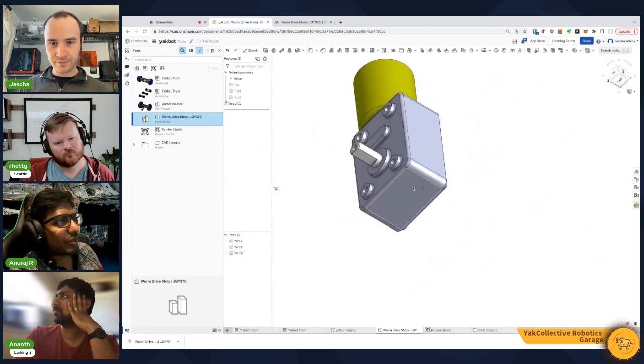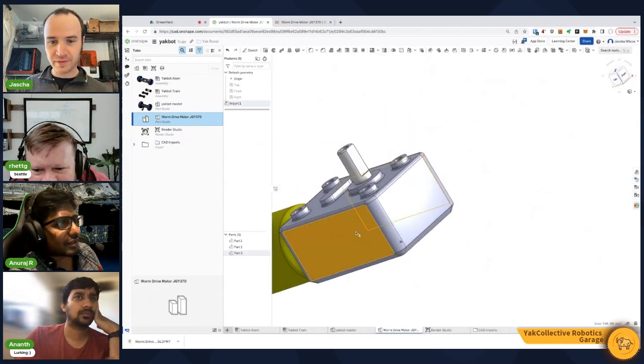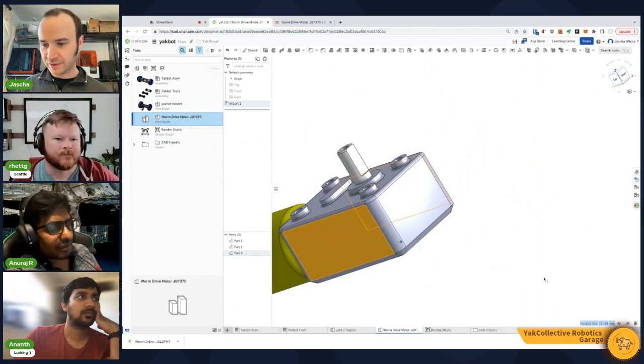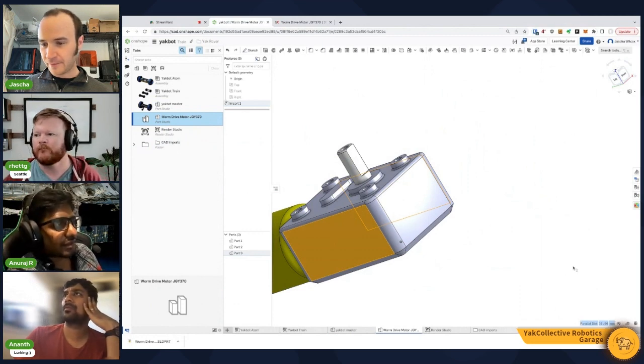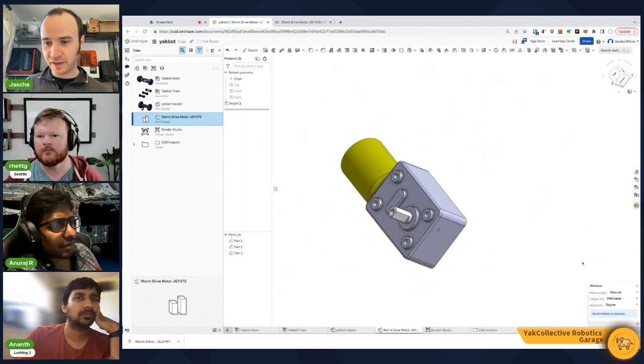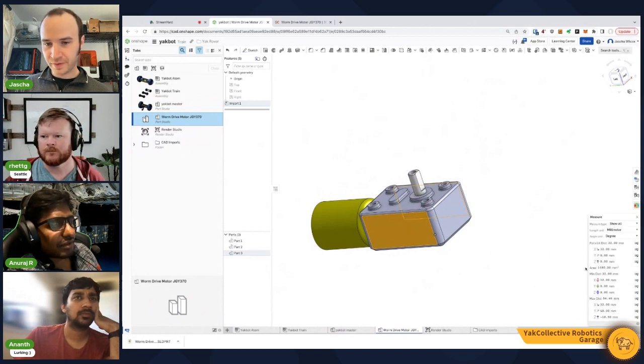Where are you looking at the dimensions? Oh, sorry. When I click two faces, down here on the lower right hand side, this right here, parallel distance. Onshape does give you that info at a glance. If you want more measurement info, you can do this, and it gives you a bunch more information.